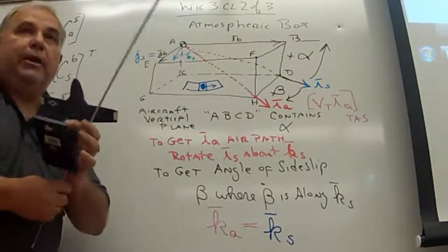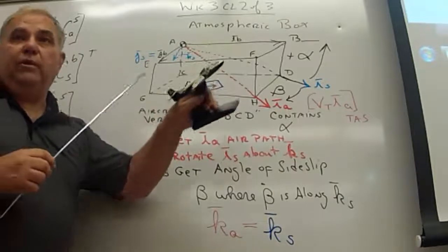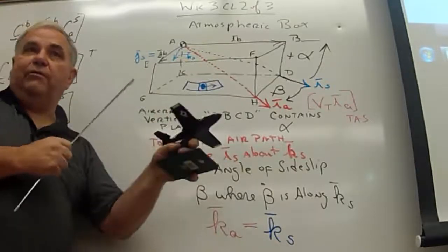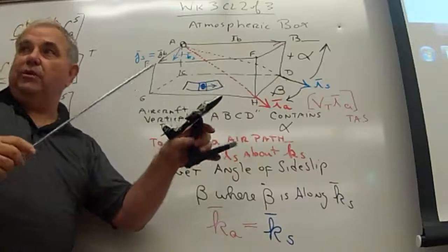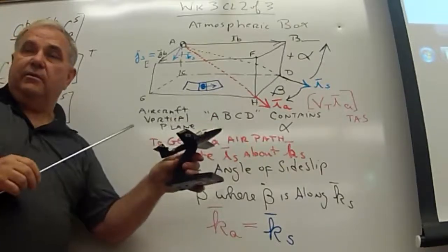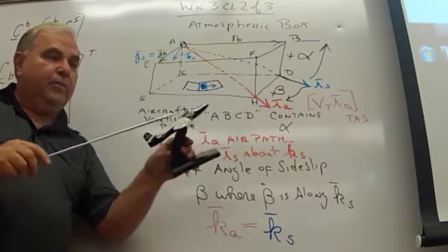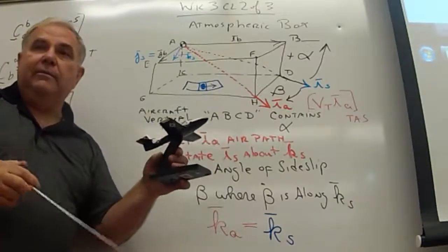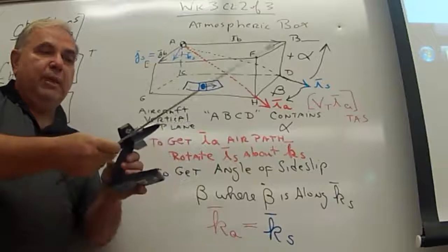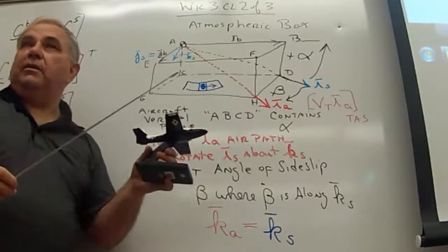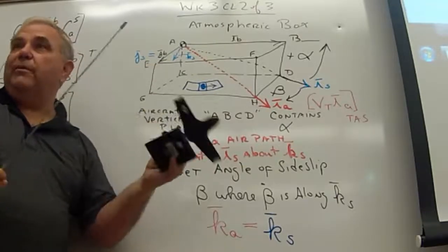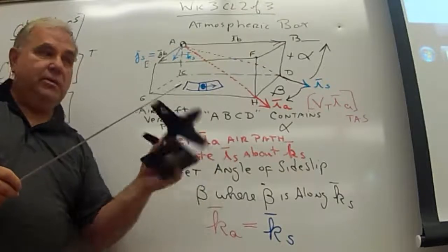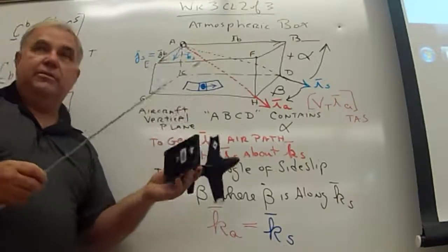Well, in a small airplane, the airplane will tend to roll. You'll have to hold opposite control to keep the airplane from rolling. You'll see too much relative wind on one wing versus the other. In a fighter airplane like this, or an F-4 or an F-18 or a modern aircraft, too much beta will depart the airplane. It will go into a spin entry automatically. Weird spin entry, sometimes inverted, sometimes uncontrollable.